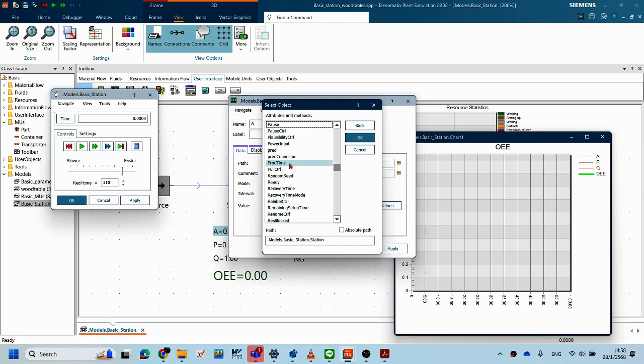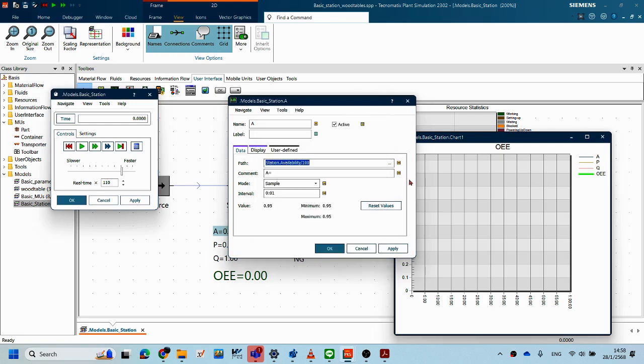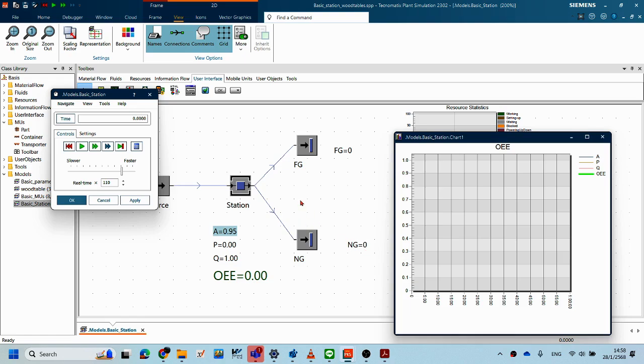The same process: drag the display to your workspace, drag the workstation and the station to the display, click the part bank box, click the three dots and select the variable you need to show on the screen. This is the way to define a new variable and specific variables you need to show on the display.